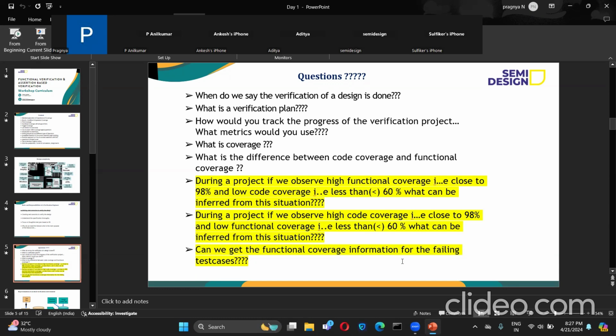If we observe any issues in particular test cases, we again go and make the changes. Here the regression cleanup will have the main focus: if you modify something for one particular test case, it should not affect the environment of the other test cases. So the main catch in solving regression failures is that any change you make should be done in a very generic way, right? That is one of the things we have to keep in mind when it comes to regression. And the other metrics are using coverage.